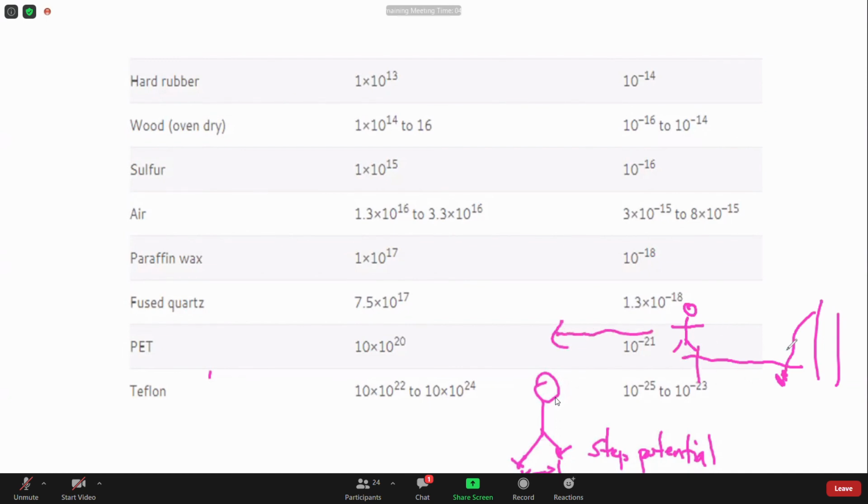The shorter the distance from the grounding point, the shorter the length, and the smaller the resistance. So your goal is to move as far away as possible so that your total length from the point where the wire is cut to your final position is long. If your length is long, you'll have a bigger resistance.